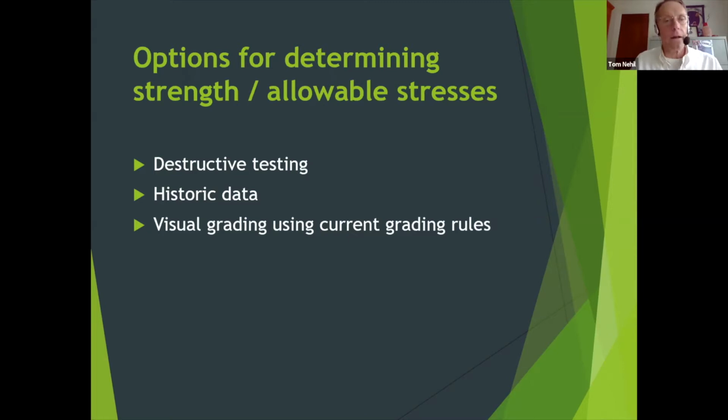Full-size lumber and timber contains natural growth characteristics or defects, and those are what really drive the allowable stresses that we use. So destructive testing is really not a good option. We'll end up destroying the building that we're trying to preserve.